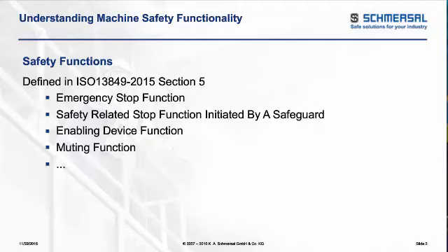What tends to happen a lot of times is you start the process by performing a risk analysis on the machine, identifying what the hazards are on the machine, and figuring out what level or quantitative approach those hazards need to be remedied to when it comes to a safety aspect. What type of guarding do you have to put on there? Are there gaps in the guarding? Are there gaps in the controls and the wiring of those controls?